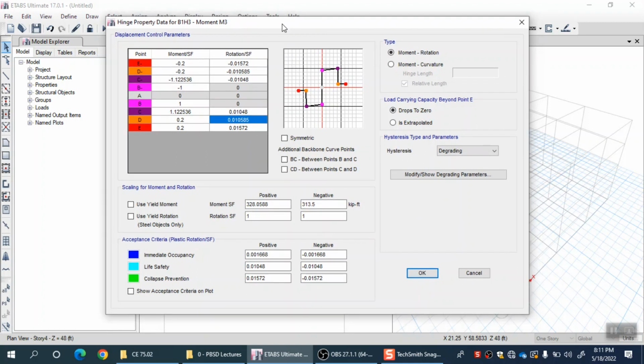But now in the latest version of ETABS, I think they have already put this option while defining auto hinge, right? So now even that effort will not be required to convert it into manual and then change its hysteresis behavior manually. In the latest versions, you have that hysteresis option directly in the same form where you define ASCE 41 parameters, right? So if you want to provide a particular hysteretic behavior, you can define it there, and then your auto hinge will have that hysteretic behavior.